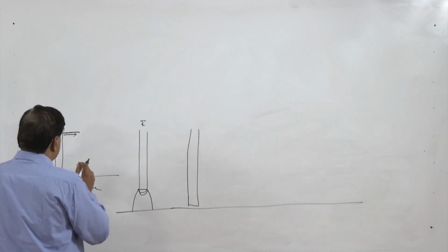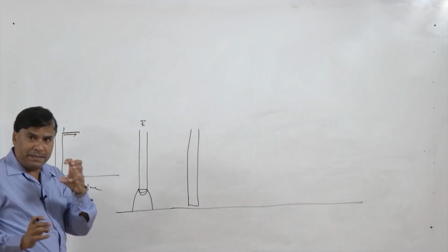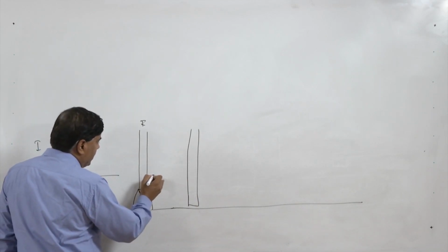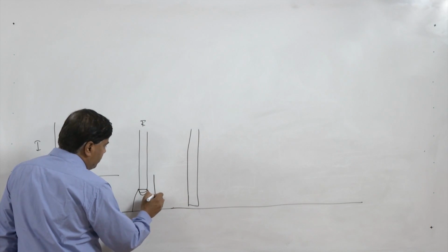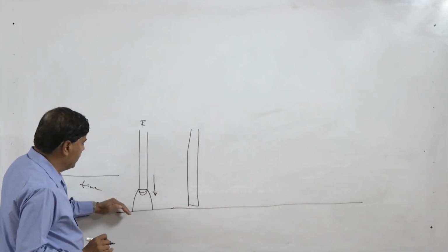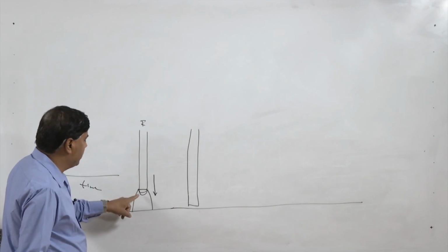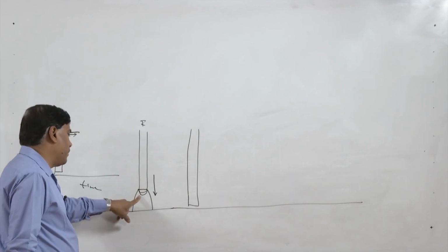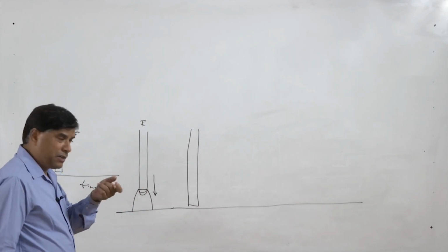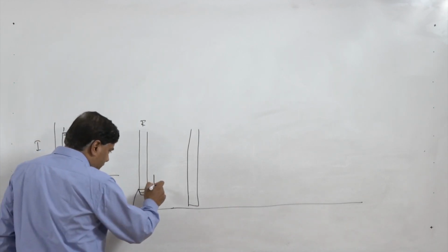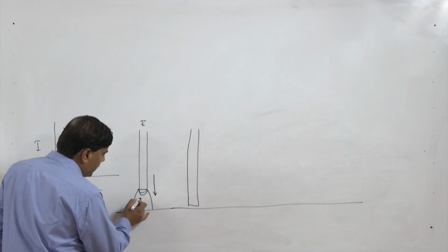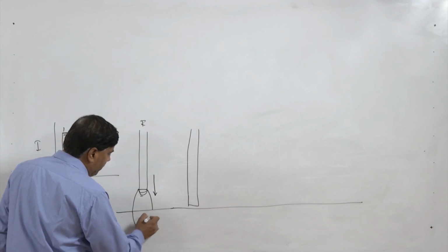So once the sufficient melting has taken place and the drop has been formed, then in the next step the electrode is moved forward. Once the arc developed a drop of the molten metal at the electrode tip, and once the drop is of large enough size, the electrode is advanced. As the electrode is advanced, the drop will touch the pool.